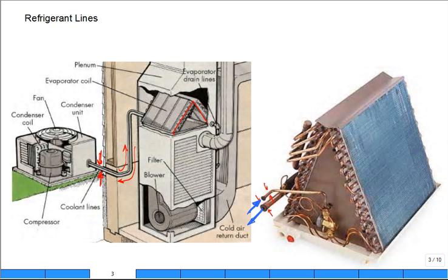So the liquid requires smaller cross-sectional area for the same mass flow rate than the vapor. The vapor has a larger specific volume or lower density, and it requires a larger cross-sectional area, hence you give it a larger diameter.